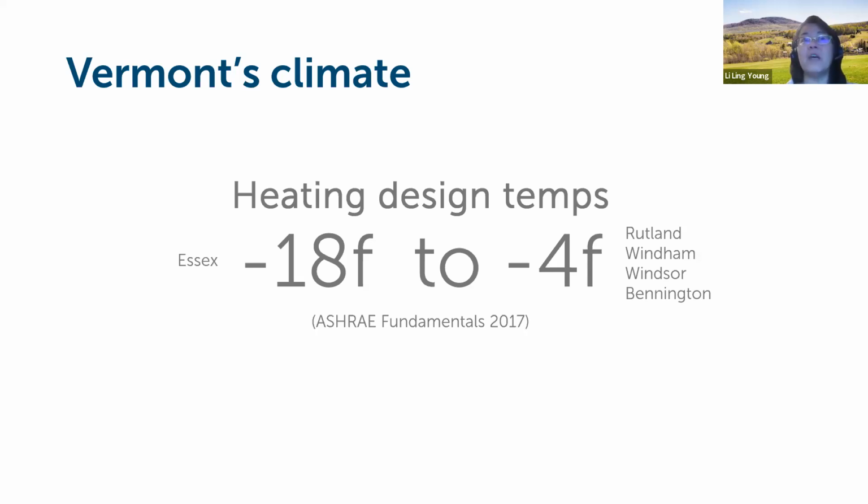And the amount of buildings that are being built in Essex County and the amount of buildings that are getting new heating systems in Essex County is relatively small. So if I see a whole lot of design work being done with a design load of -18 and colder, I know that people aren't using the appropriate design temperatures to calculate a load accurately. Most of our counties are either -11 or -8. So that's everything else, including St. Albans, Lyndonville, Montpelier, Middlebury, Randolph. Those are all between -8 and -11. And then, of course, the 4 southern counties, those are the warmest, and they have a design temperature of -4.